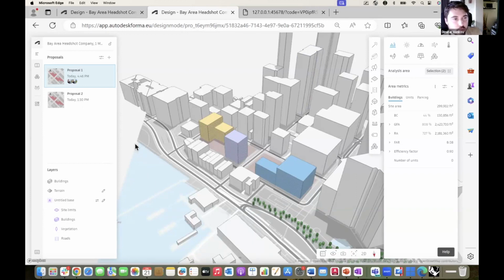Yeah. One of the questions was what kind of geometry should I convert my Rhino elements to before sending it to Forma? I would suggest you don't actually convert it yourself, but instead you keep it as the original geometry that you modeled it in Rhino. So either a solid or a subdivision or fully surface.